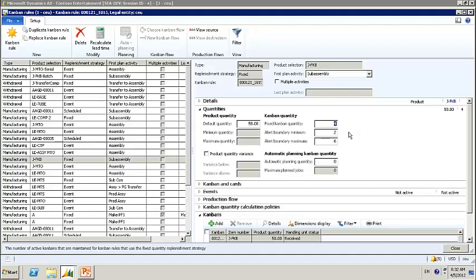And this is real important. I want you to remember this, because when we come back in a little bit, we're going to do a Kanban calculation. And basically what that calculation is going to do is say, how many of these fixed Kanbans should you really have? It's assuming that your default quantity is basically your bin size. That's a set size based on the bin or based on a convenient handling size. So it's not going to tell you to change the default quantity, but it's going to suggest that you either raise or lower the number of bins of that particular item that you have.